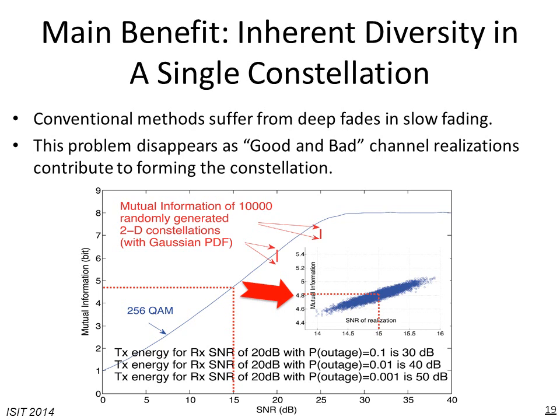The point is that the mutual information has a span of about 0.2 dB from the worst to the best. For example, for 20 dB, it can go up to a little bit more than 256 QAM. The majority of cases is less than 256 QAM, but it's never more than 0.2 dB below the 256 QAM.